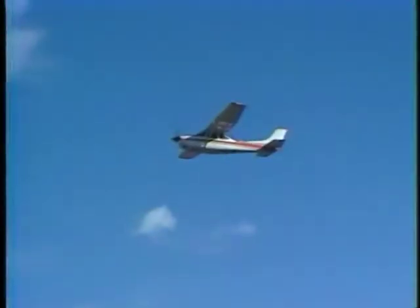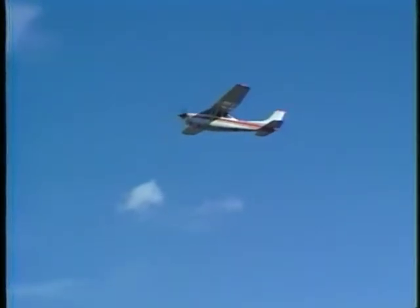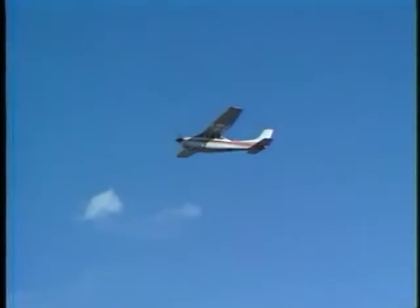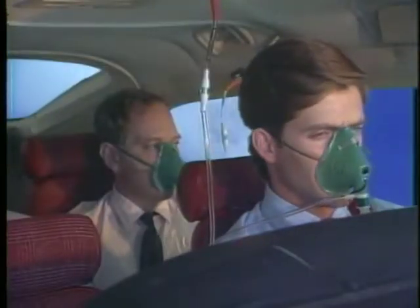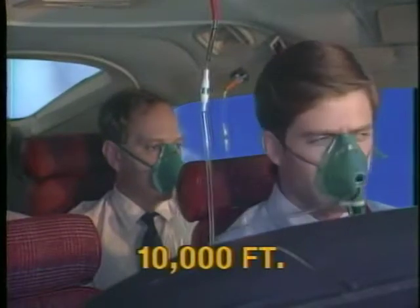Since hypoxia impairs judgment and may not be easily recognized, it is very important to take corrective action before hypoxia develops. The FAA recommends that oxygen be used above 10,000 feet during the day and as low as 5,000 feet at night.